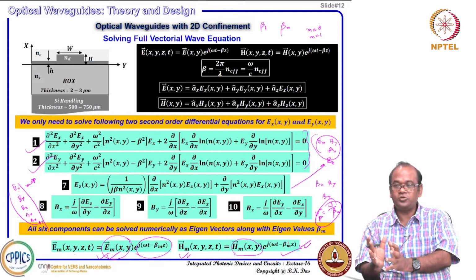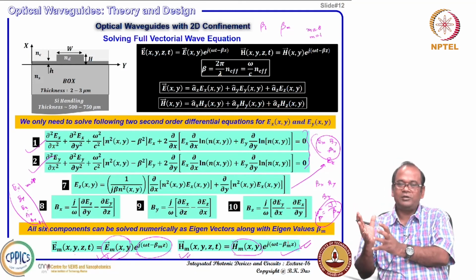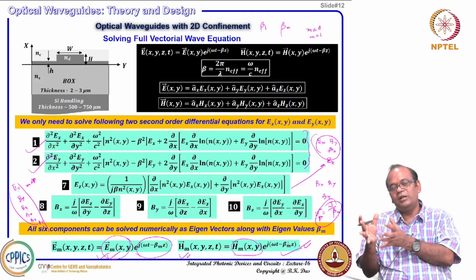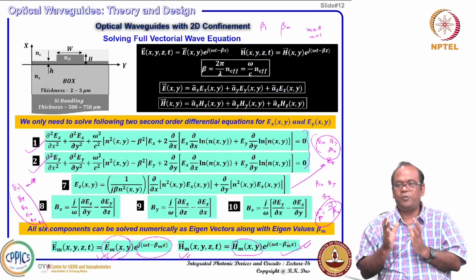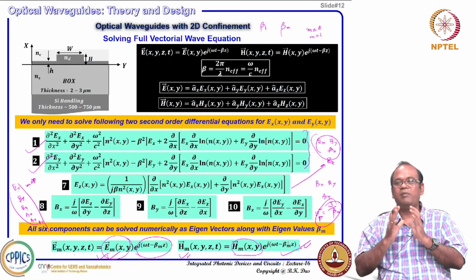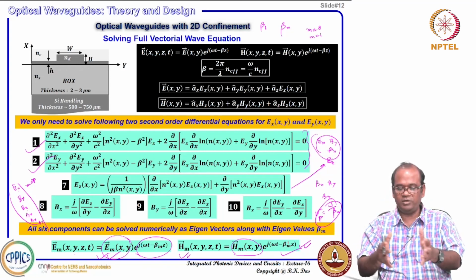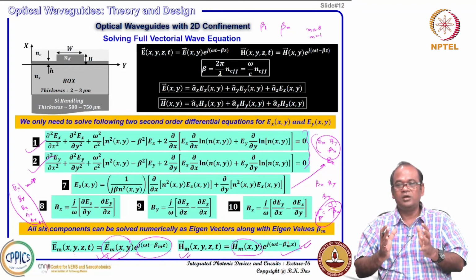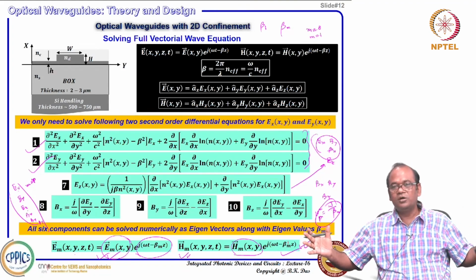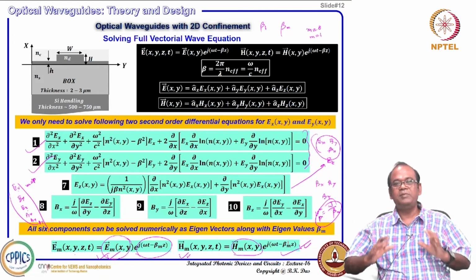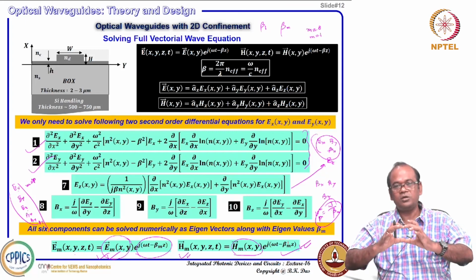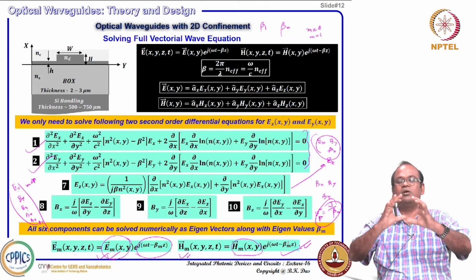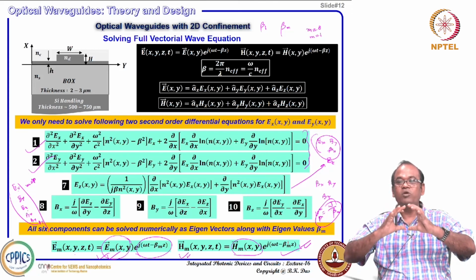So we are very close to developing photonic integrated circuits, and before going into that detail, we will be learning how a mode actually propagates. Suppose in a waveguide you get multiple mode solutions when you solve these things. Some of them will be very confined and well defined within the waveguide, and some of them are lossy, just leaky modes. We will not concentrate on leaky modes; we will be exciting only the confined guided modes.